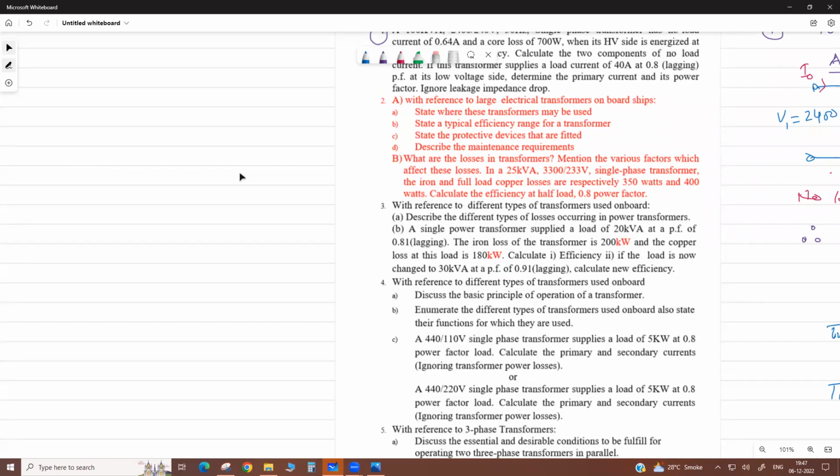Protective devices. So on a dry type transformer, you know, under voltage, overload, short circuit. Then there is temperature, continuous monitoring of winding temperature. On the scanner there is continuous monitoring, we put the thermocouple on the windings in dry type.